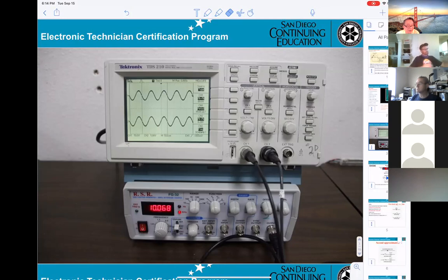They will be connected to the oscilloscope, these two channels. Channel 1 displays the input and channel 2 will normally display the output. Okay, you want to measure voltage, peak to peak, frequency, RMS. Instead, you have to do your calculation. The one we're using at the school, they do everything for you.